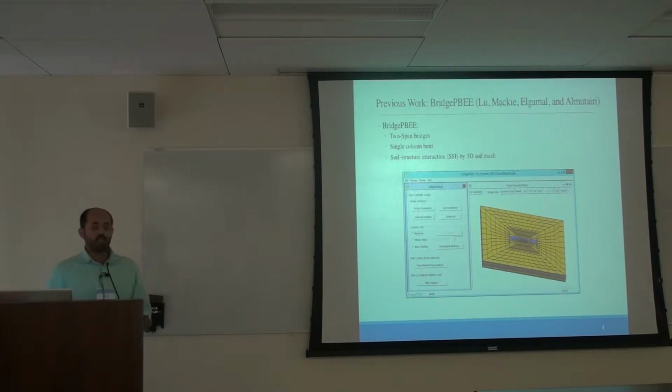In the previous work by Dr. Jinshi Lu, we combined the nonlinear time history analysis with the PBEE applications using a software, Bridge PBEE. However, this software is limited to 2-span bridges, single column bent. The good thing about this software is a user interface for OpenSees, where the soil structure interaction is modeled using a 3D soil mesh.